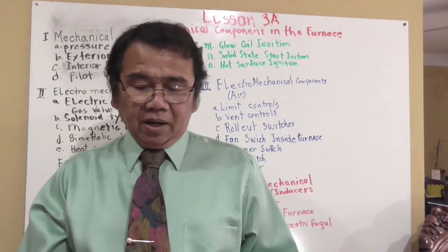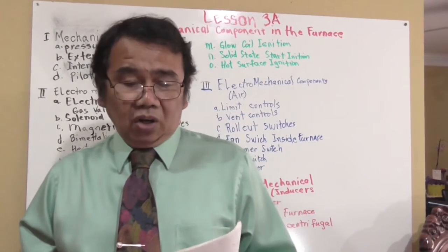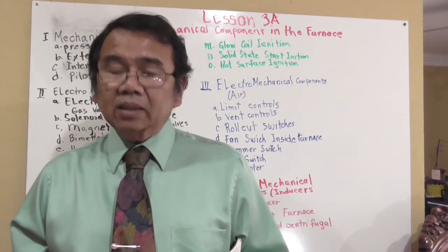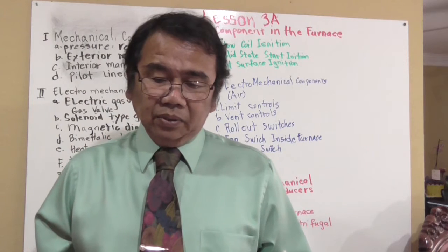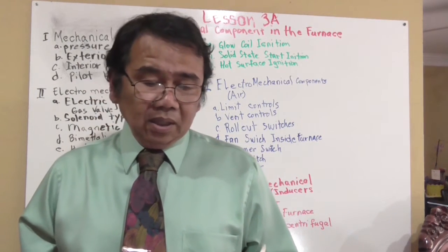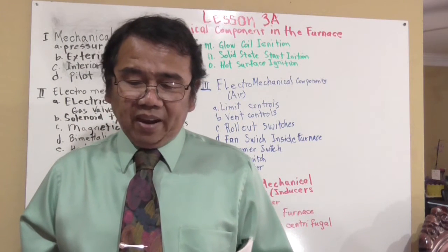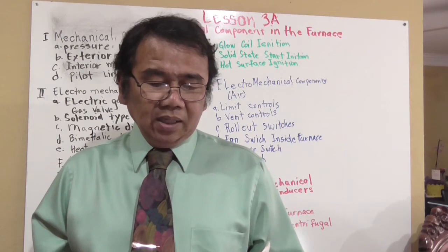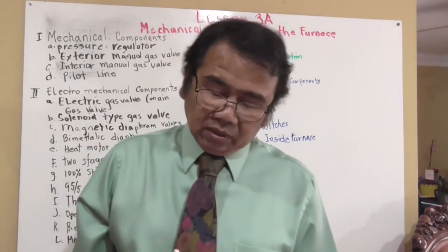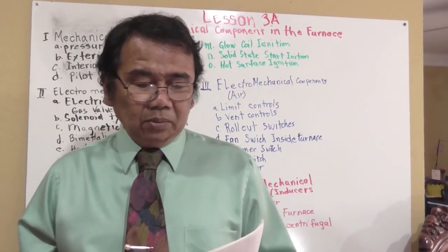And there are normally 5 low voltage terminals on the face of the transformer. They are R, which is the secondary, W, which is the heat, Y, which is the cooling, G, which is the fan or auto, and C. No, C is equal to the secondary common.